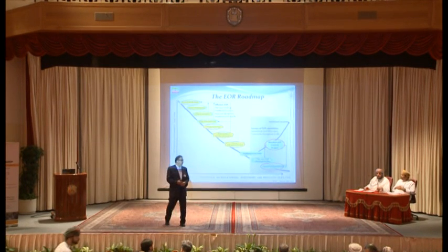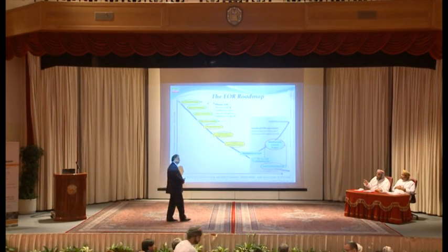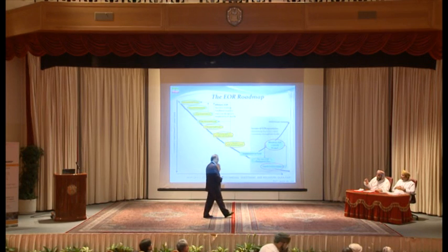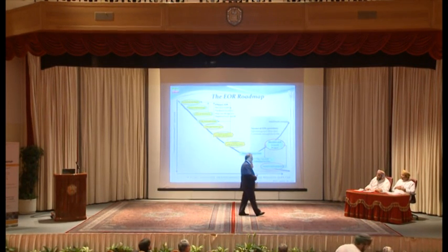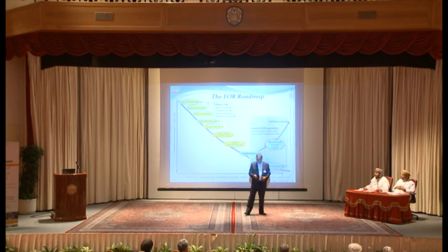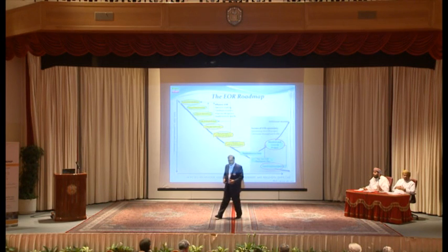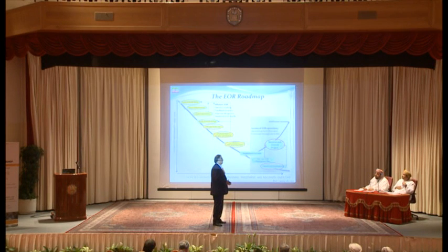Yeah, I have one question. Do you have a tensiometer, an IFT tensiometer, which measures IFT under reservoir pressure? Yes, this IFT system uses the pendant drop method. The maximum pressure for the system is 10,000 psi, but the applied pressure of the equipment is maximum 7,000 psi. Okay. And reservoir condition temperature 150 degrees centigrade.